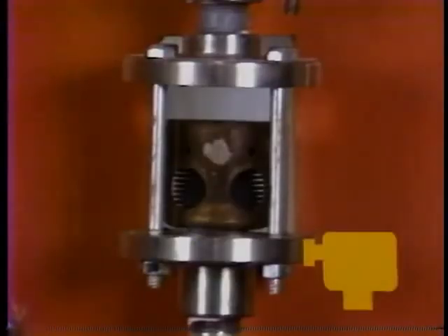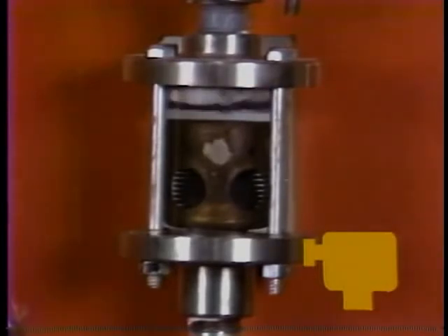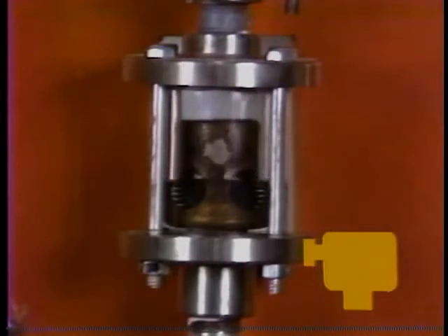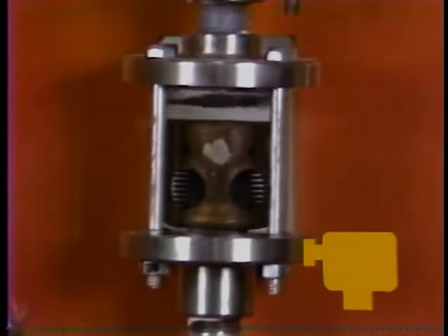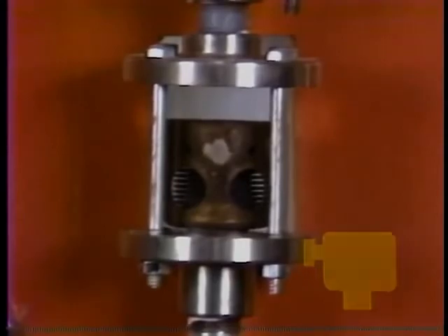Bellows traps can also have a good service life provided they are protected against water hammer. They can be piped in any orientation and they have good startup characteristics. Bellows traps do back up condensate, however, and the increased corrosion and water hammer potential may be a problem.